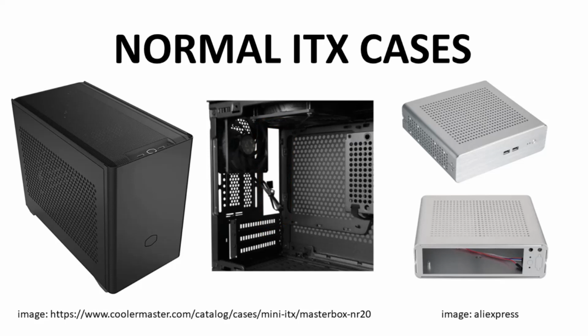A mini-ITX build can be as small as this tiny case on the right. It's around 200 by 200 millimeters. The minimum case height is about 60 millimeters, which still gives room for the standard sized I/O rear panel cutout clearance of around 45 millimeters. You probably can't include a discrete GPU in this tiny case, but you can build a PC in there.